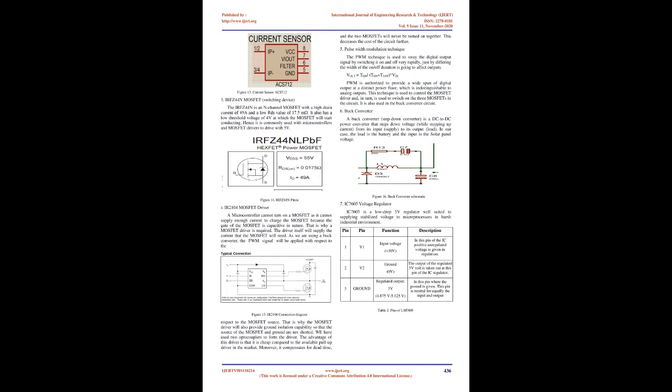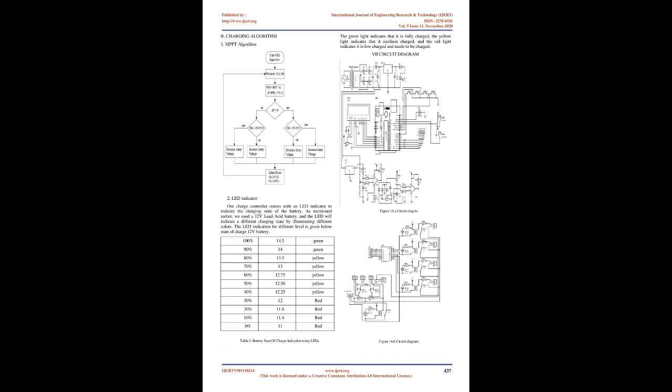Solar panels are nonlinear sources of power. The figure below shows the output current and voltage, the IV curve, for a particular intensity of light falling on the solar panel. The power output at a point PM is the product PO equals VM * IM. MPPT is about finding the point at which the power output is maximum. This normally occurs on the knee of the curve.